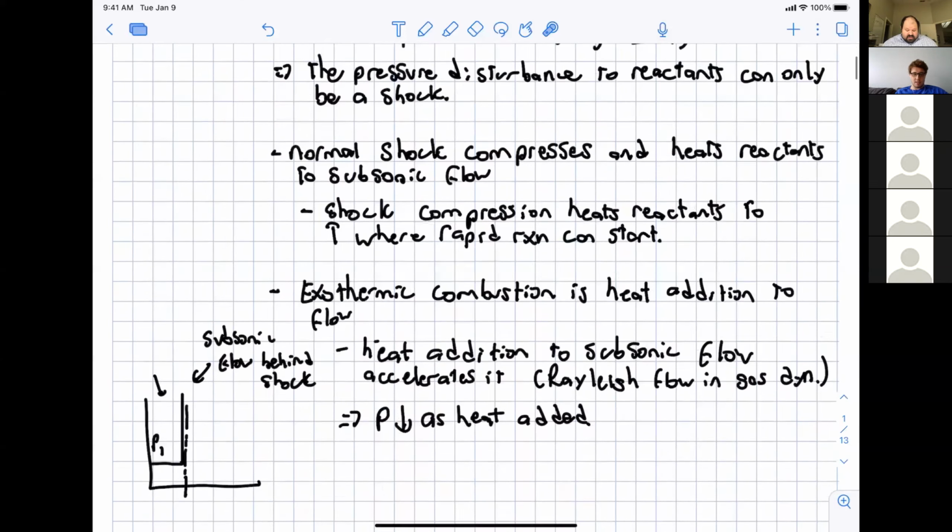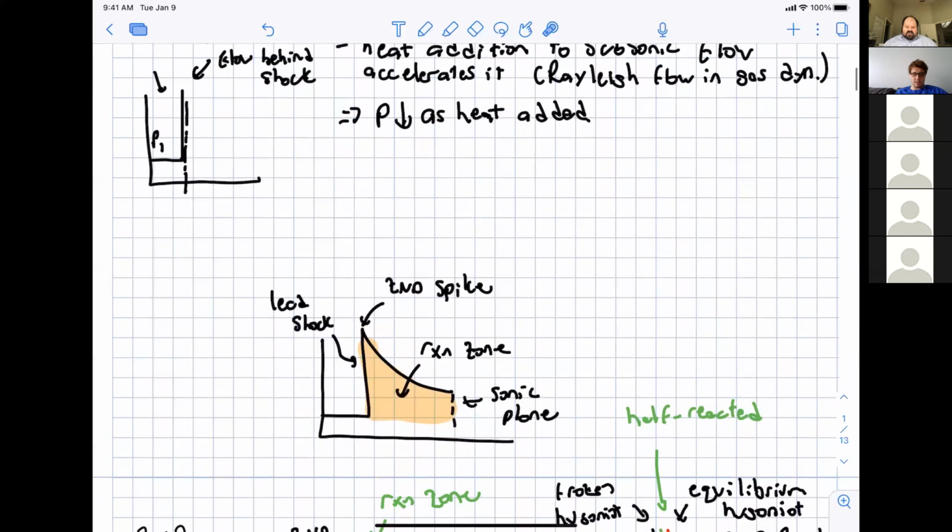So they realized that there's really only one structure that you could have that is steady, and that is if we have a detonation moving to the left, we have reactants here, and we have our shock wave propagating to the left. That's going to shock, heat, and compress the reactants to the point where they start to burn. The point where you have the shocked reactants but no burning yet is called the ZND spike.